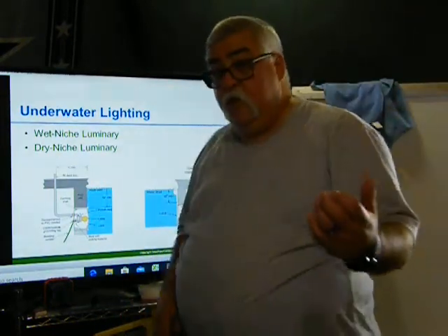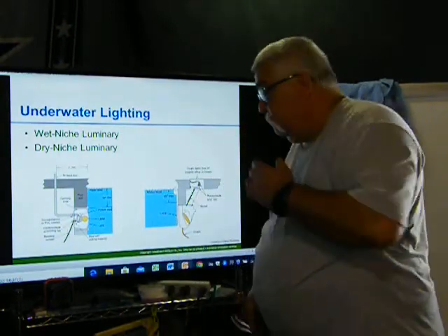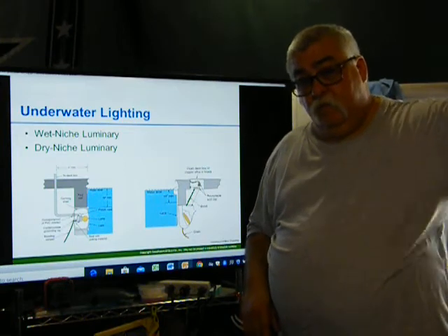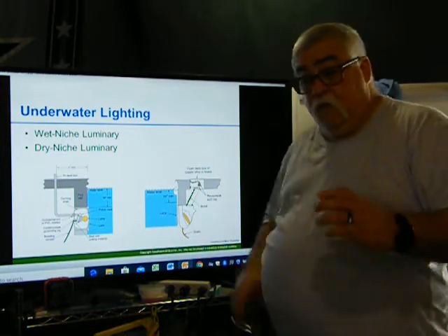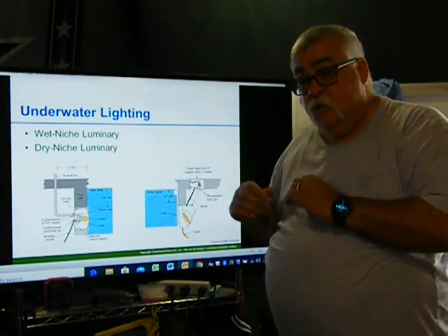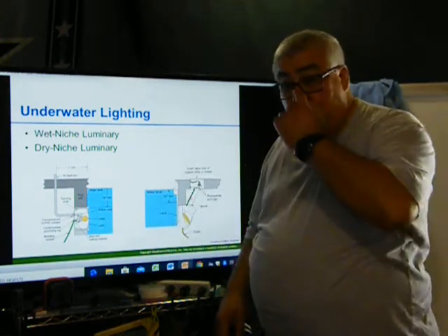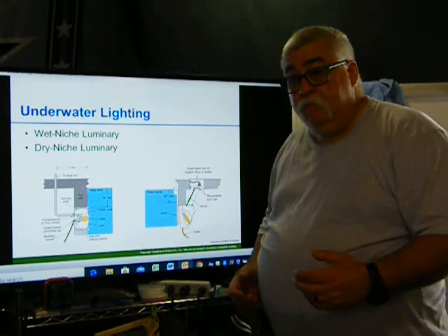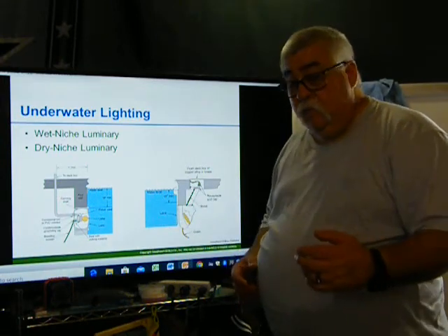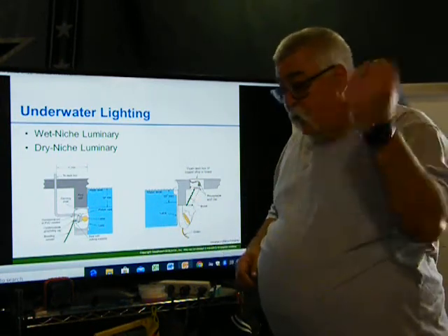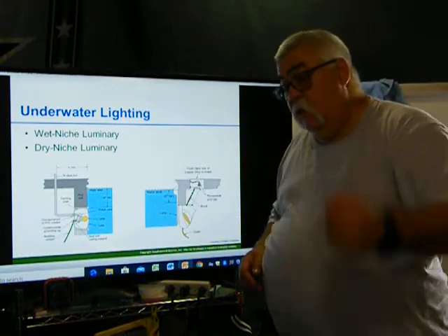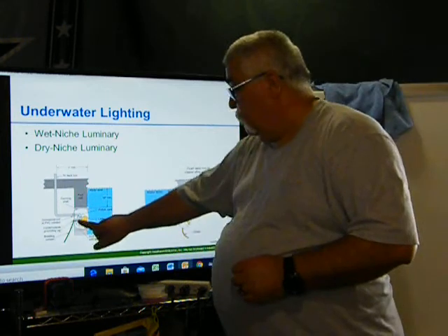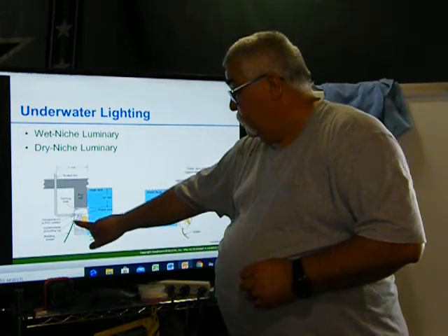Inside here it went to a J-box. We had a J-box 10 feet outside the pool area, 12 feet above the water level, and that's where the J-box for this light was. This light comes with a cord, so we would order a 20-foot cord, a 25-foot cord, whatever we needed, and we pull the light in. We take the fish tape in, have a string in there, whatever we had, and pull that cord through. Within that cord, we also pulled the grounding wire.